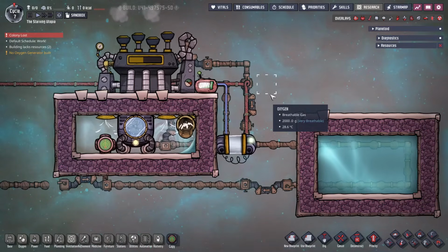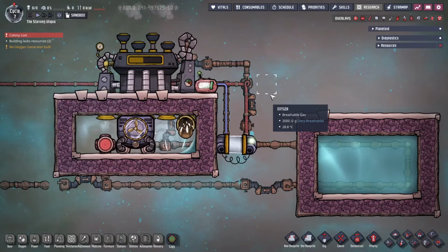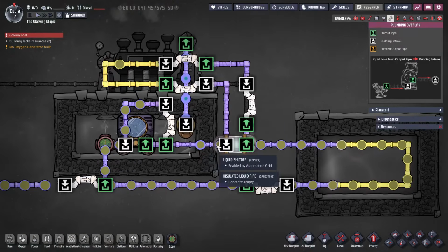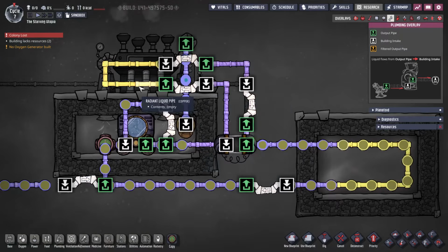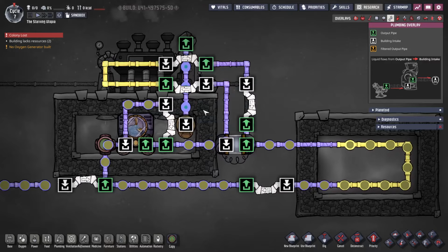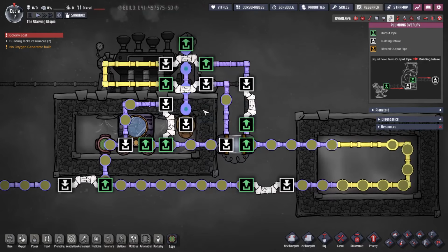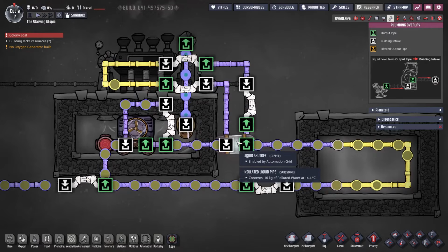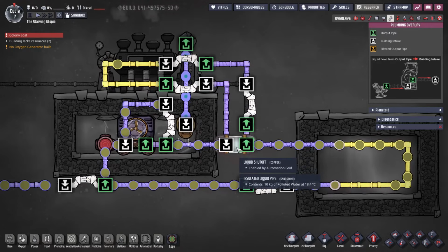The final bit to add to this design is cooling for the steam turbine itself, which will overheat if we don't add this. After the point where the bypass has rejoined, we can take a pipe run and simply loop it behind the turbine, watching out for the turbine output pipe. Assuming your coolant temperature is below 100 degrees C and also not too cold, this will be simple enough, but if not, then you may need extra control.